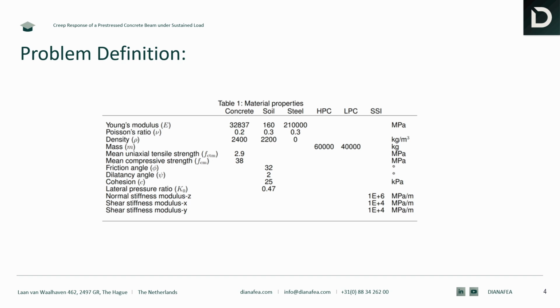For the compressors, we are simplifying the setup by considering two mass point objects in Diana. They sit on a rigid massless steel frame which helps us to isolate the dynamic behavior of the system. In this model, to capture the interaction between the foundation and the soil, what we call soil structure interaction or SSI, we are using a no tension stiff interface. This basically means that the soil and the foundation can push against each other but not pull apart.